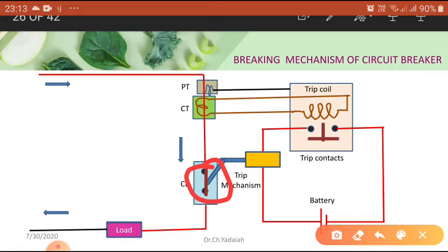The hydrogen gas cannot remain in molecular form and is broken into its atomic form, releasing a lot of heat, so the arc temperature reaches nearly 5000 Kelvin. The mixture of gas occupies a volume about 1000 times that of the oil decomposed.